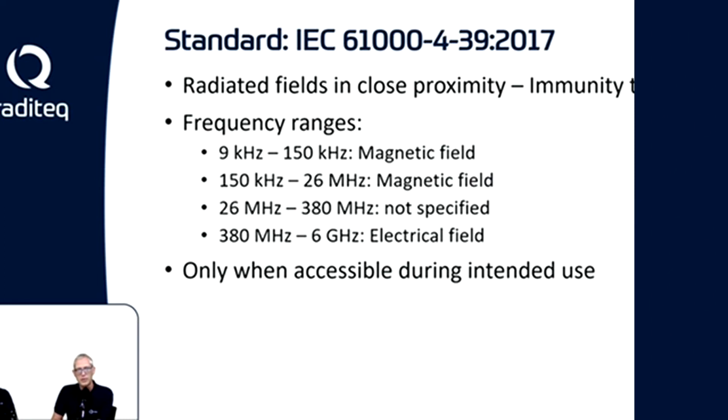Another standard that describes the magnetic field testing is the IEC 61000-4-39, and specifically I'm now referencing the 2017 version of that. That standard is specified as being the radiated fields in close proximity immunity tests, and this standard is not only for magnetic fields, it's also for electrical fields.